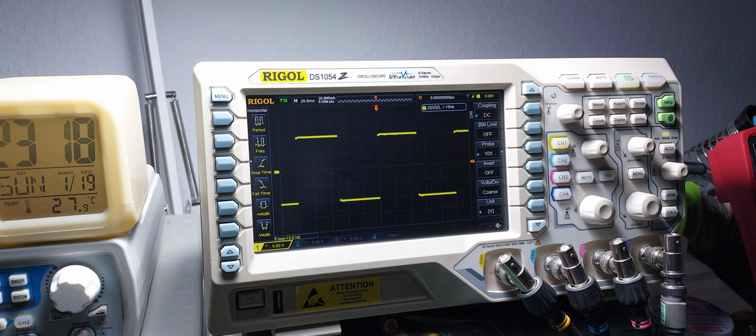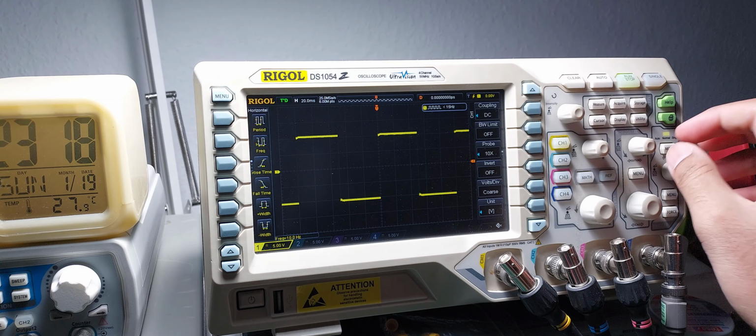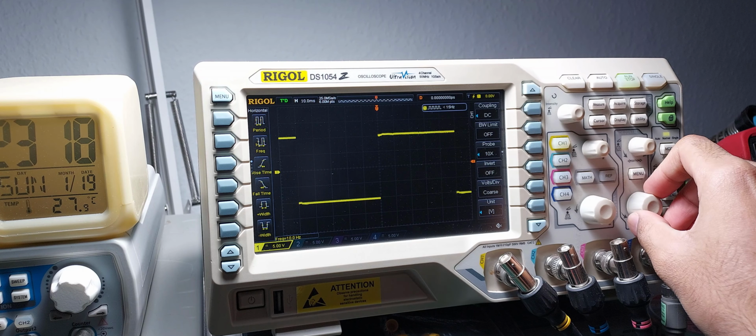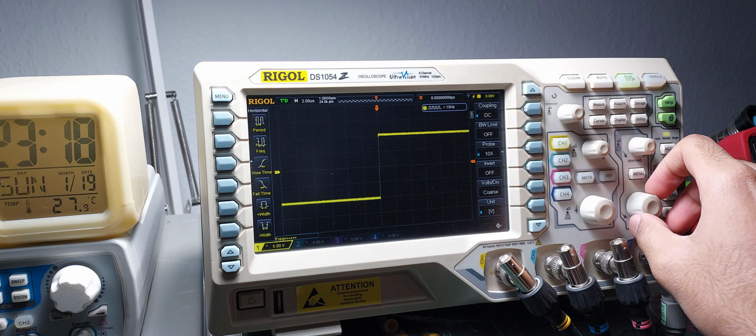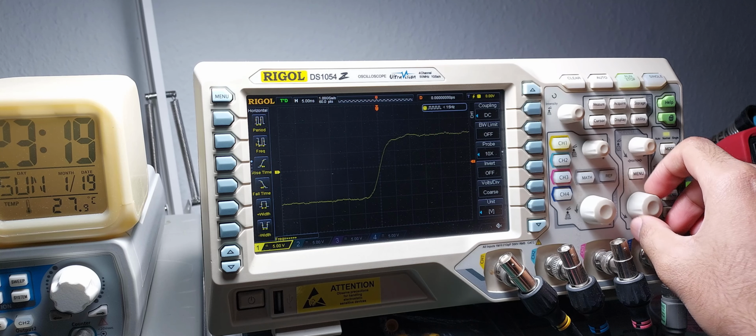I will take this opportunity to point out that modern analog switches are blazing fast. The propagation delay is often mistaken for switch rise time. The latter can be estimated based on the -3 dB bandwidth specified in the datasheet.